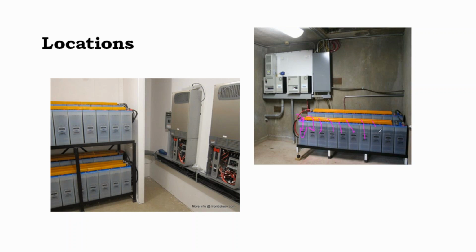Now, it may be something that can be done in 15 minutes, but how are you going to take the specific gravity reading of this battery in the back? You can't access it. You have to lean over the battery bank. And so if you have a particularly fastidious inspector, he'd say no. If you have to maintain that, you've got the electric code clearance requirements to consider, which is,